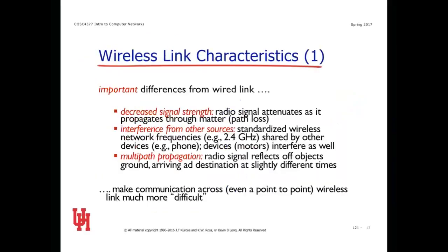Okay, there's some really cool algorithms in wireless. It's the most error-prone medium that you can have. I know of no other that's more error-prone, particularly in the unlicensed spectrum, but it also applies to the licensed spectrum. There's nothing to prevent interference from nature, and there's very little to prevent interference from other man-made objects that are not intended to be communications devices. All kinds of motors, all kinds of things like alternators generate magnetic fields, generate radio spectrum, but they're not prohibited because they're not built for communications. So you must accept the interference that they generate.